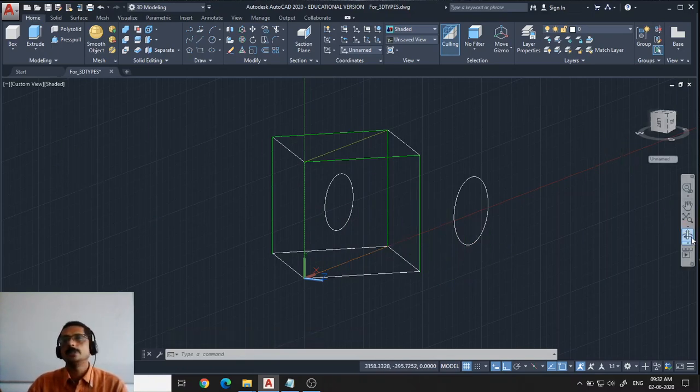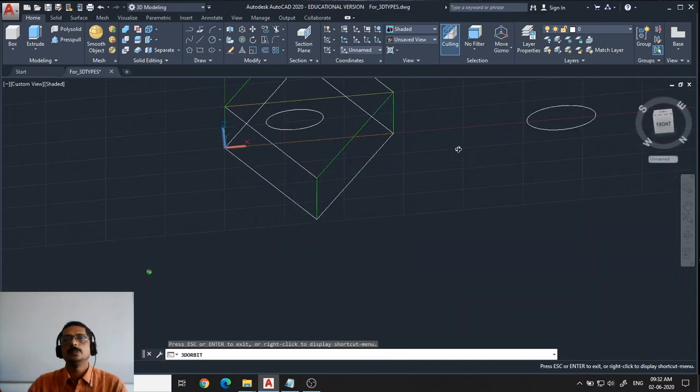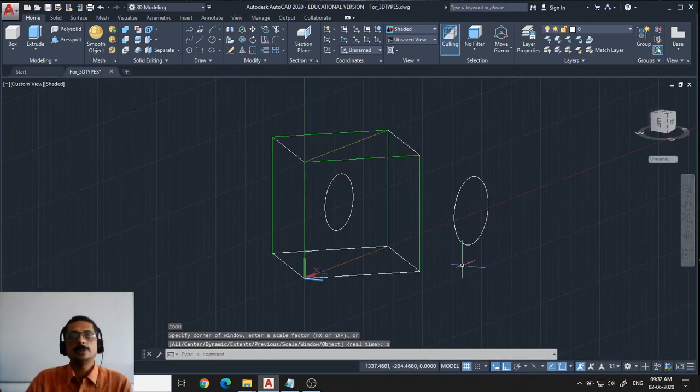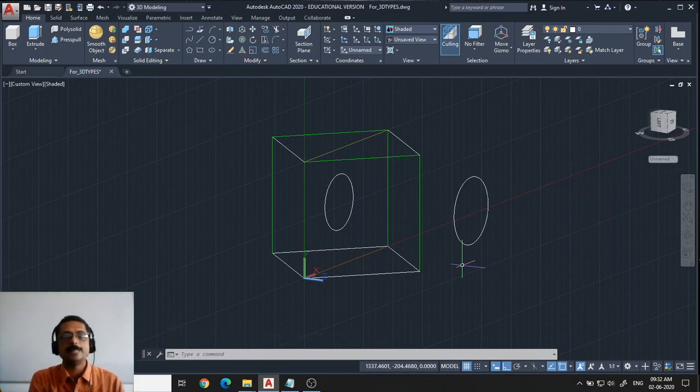Right? You can rotate it and see it is on this plane itself. So I have drawn on that plane. Okay, fine. So this is about the different planes in which we are going to draw, or we can say different UCS. The other option we have is named UCS: once you create a UCS, you can save it under a particular name that can be used later.